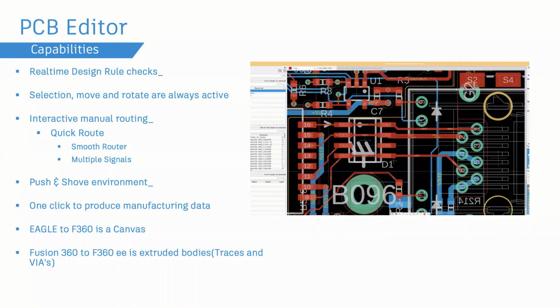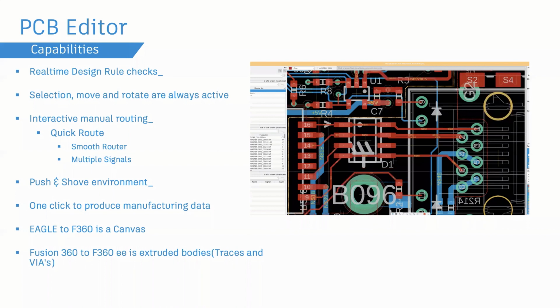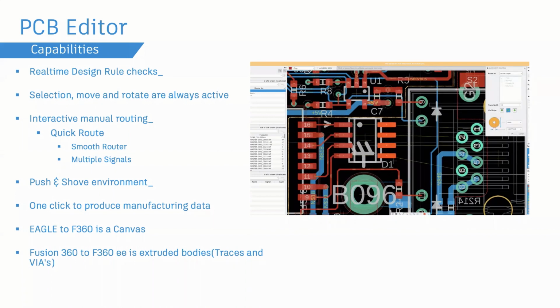Okay. Now, kind of neat, very useful, speeds up a lot of things. So if you've got a large bus and straight connections going from one component to the other, you could just select it and give it the direction. Let's say you want to do a little 45-degree bend because you want to place other bodies in that area. You could go around them and influence that route as well.